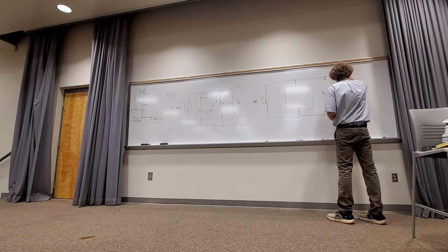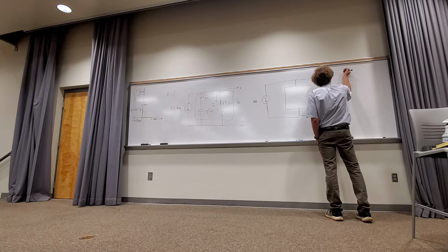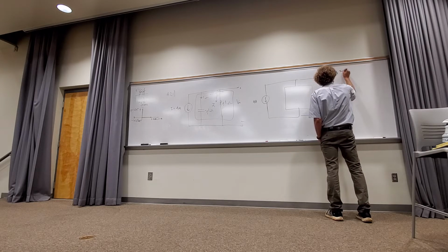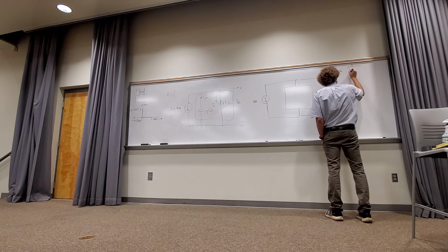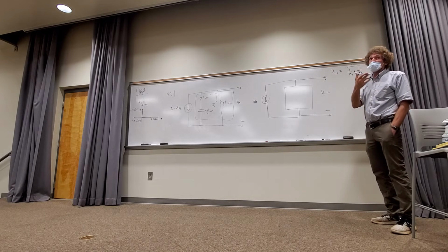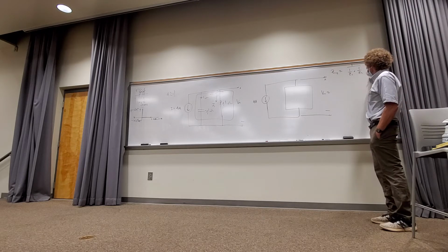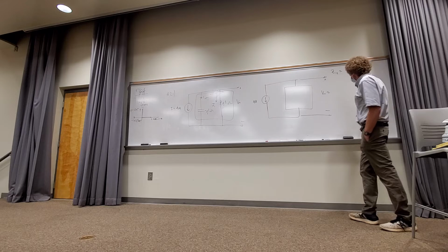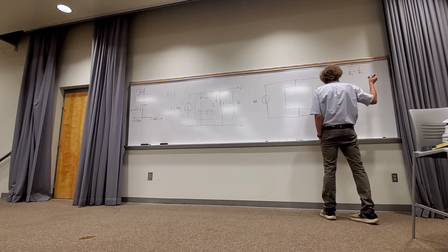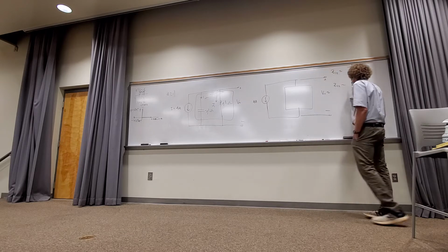So do you remember how to get this? Well, in general, if we're talking about two impedances in parallel, Z1, Z2, one way to do it is 1 over Z1 plus 1 over Z2. Correct, class? That's one way. That would be just like resistances, right? And if there were more than 2, you would add 1 over Z3 and 1 over Z4.